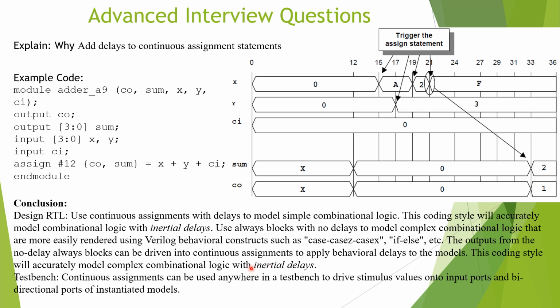Use always blocks with no delays to model complex combinatorial logic that is more easily rendered using Verilog behavioral constructs such as case, casez, casex, if else, etc. The outputs from the no delay always block can be driven into continuous assignments to apply behavioral delays to the model. This coding style will accurately model complex combinatorial logic with inertial delays. When you're writing a test bench, continuous assignment can be used anywhere in the test bench to drive stimulus values onto input ports and bidirectional ports of instantiated models.